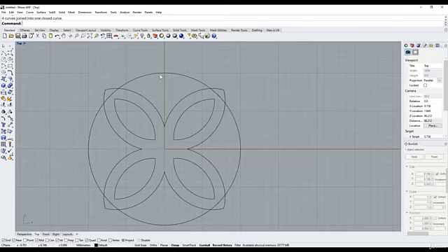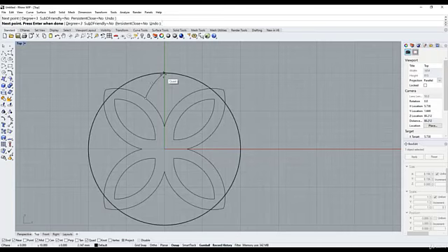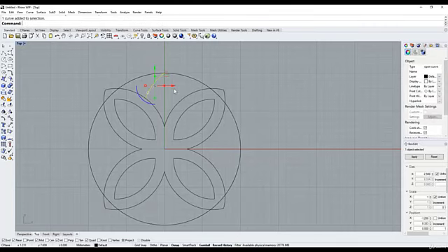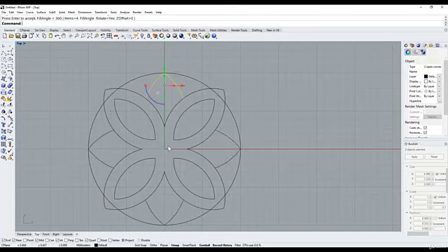Let's make some more parts to this. So we'll come over to our curve command, and I'm just going to do some freestyling. Okay, that's pretty inspiring. I'm going to mirror that across the y-axis, and then I can do a polar array, which is the command array polar, center of polar array being 0, number of items being 4. Awesome. I'm going to select both of those and join.